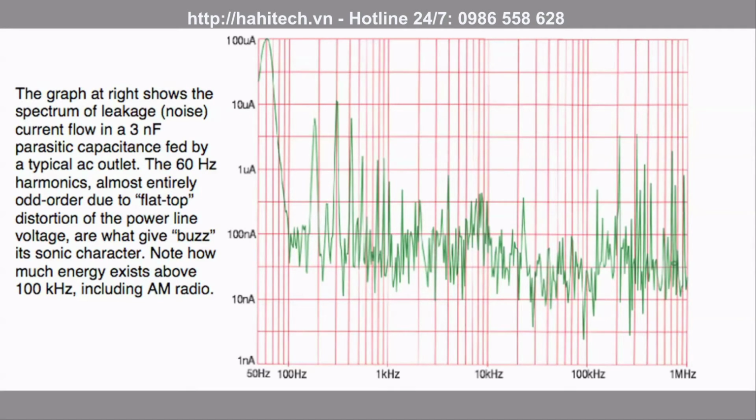So if you're using a transformer, and every transformer is going to have this, hopefully specified when you order your transformers, in terms of how much parasitic capacitance it has. And that will basically determine how much noise that thing is passing through it as a filter, but also how much is it passing to ground, and how much of a noise current is it creating on ground.